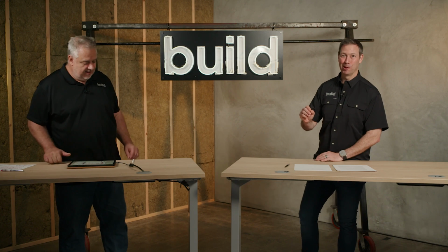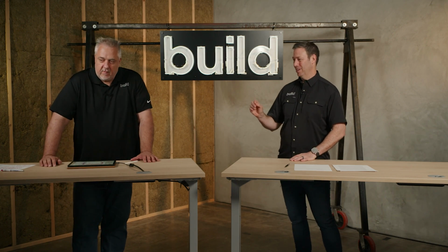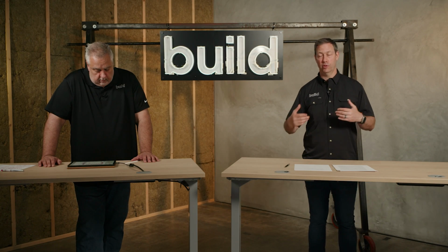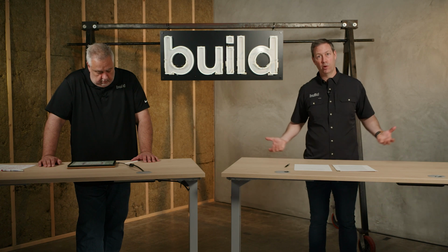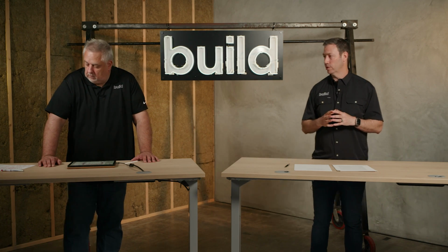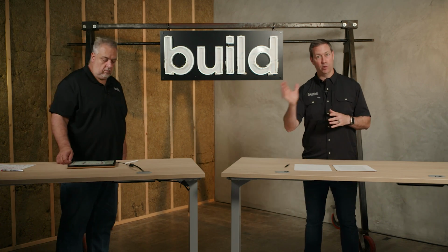I'm going to make one last point, even though I know we should be finished. But in his example here with that attic, that means that attic needs vented. If that was a front porch, if that was a soffit area that was beyond the air barrier, we'd also want to vent those spaces. Because if we did have any moisture buildup, we'd want that moisture to dry out. And this is a building code issue, and this isn't really a building code series, but any space that's outside needs to be vented.